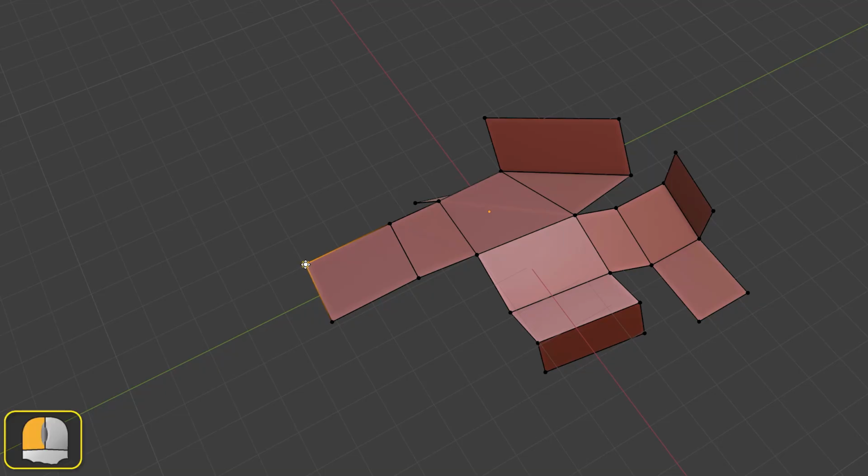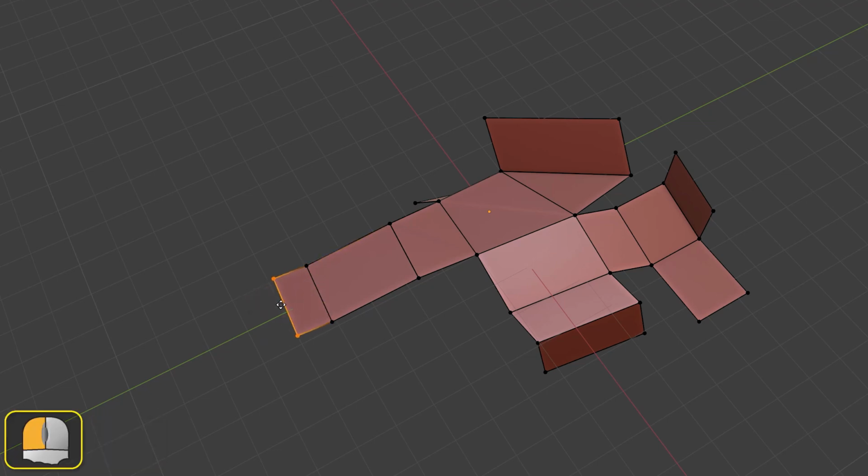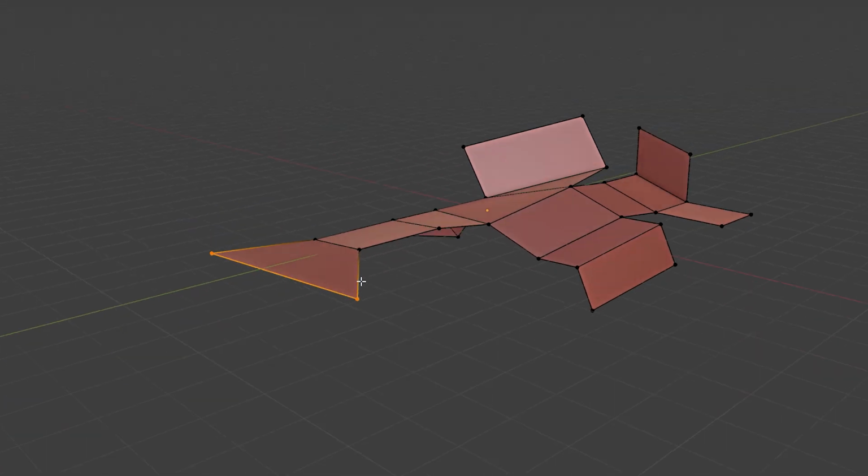When dragging a vertex, holding down the G key will slide the vertex along existing edges. With an edge selected, pressing R allows us to rotate that edge, but this will make the existing face attached to that edge non-planar. When we are creating a face by extending an edge, pressing S allows us to scale the size of that edge.